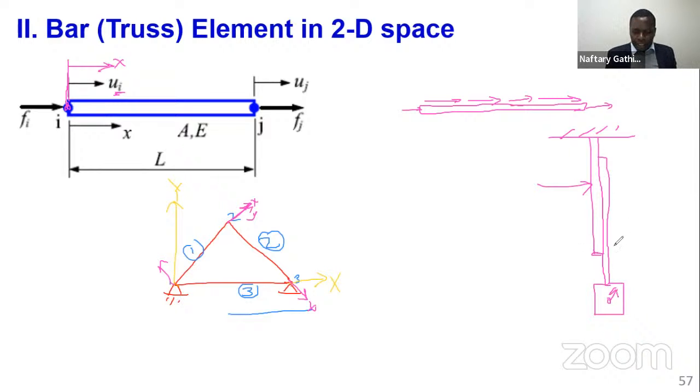So you can see this is different than when it could have just been fixed at this end, because if this is bolted or nailed, the load is distributed uniformly, although the load is acting downward, right? But if we are analyzing this member which is fixed on this wall, then it means the load is distributed uniformly along the length of the member, but axially. So when you have cases like this, and this is node I and node J here, this UDL, because we said the load is applied at the node, has to be resolved to the nodes. So how do we do this?